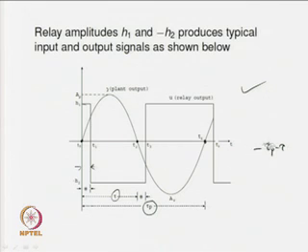So, it is possible to make more measurements from this output signal. The benefit we get from this is, what measurements will one be able to take from this output signal? We have got two peak outputs, unlike the earlier cases. For symmetrical relays, the peak amplitudes were the same, the positive peak and negative peak values were found to be the same.